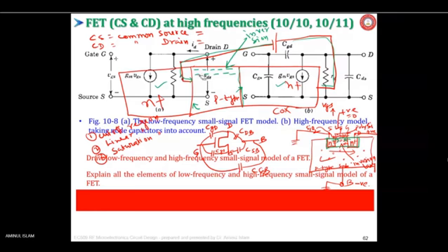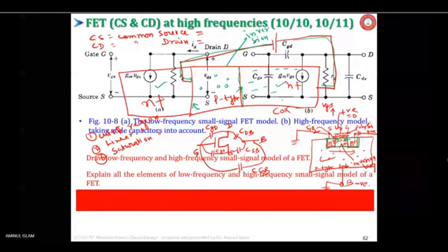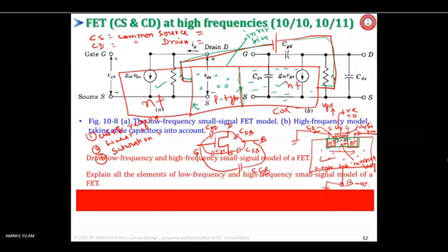Here, right now, we don't have anything. You have the holes. Here, a lot of electrons, because it is N plus type. The substrate is lightly doped, but still holes are there. So these holes will be attracted in this direction because it is reverse biased, and these electrons will be attracted in this direction. So can electrons go to this region?